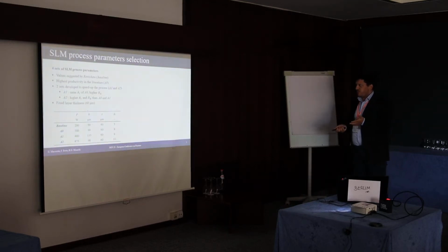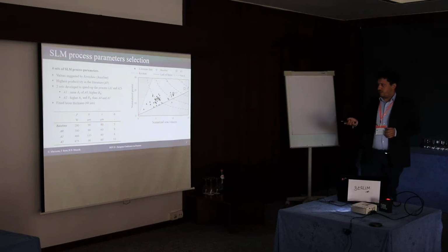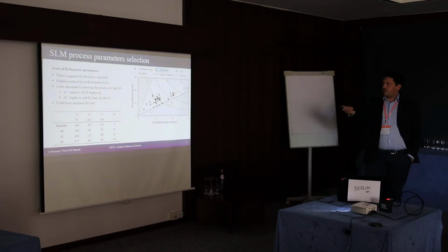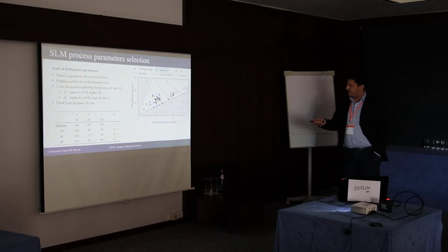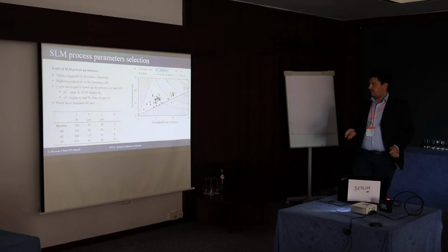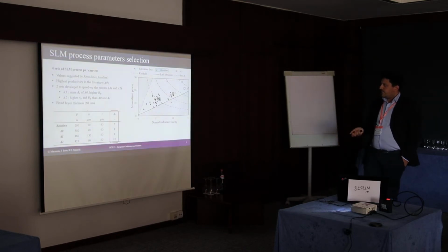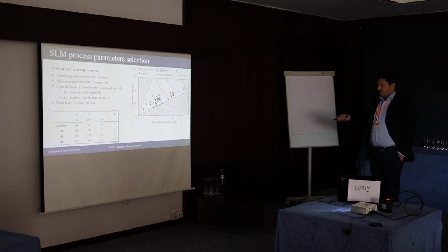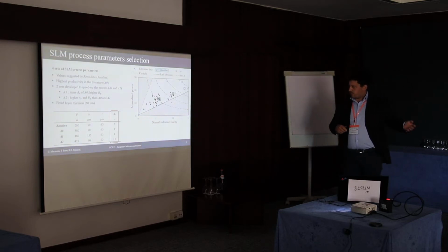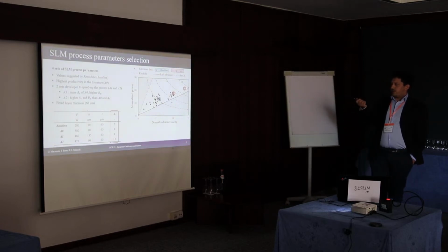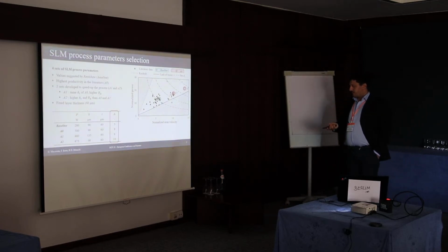We tested 5 sets of selective laser melting process parameters. The values suggested by the manufacturer of the printer, Renishaw, here called baseline, are almost in line with the standard that we can see in the market, with an aspect ratio of the melt pool of about 5 using the approach that I showed before. But we tested also 3 other process parameter sets.